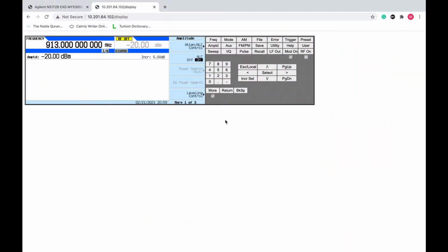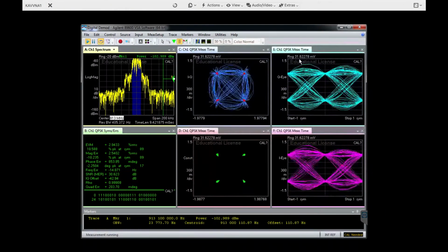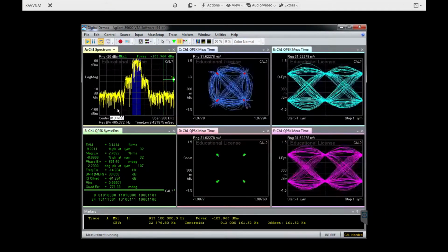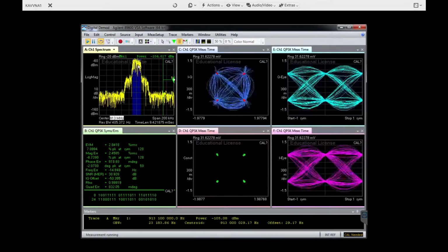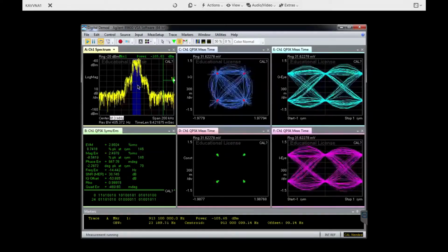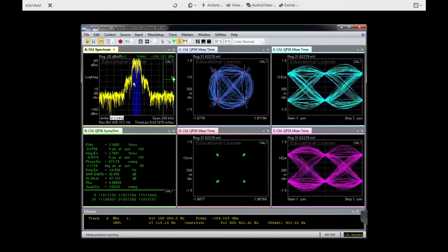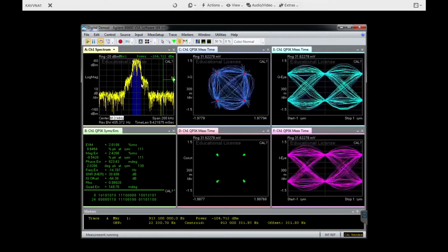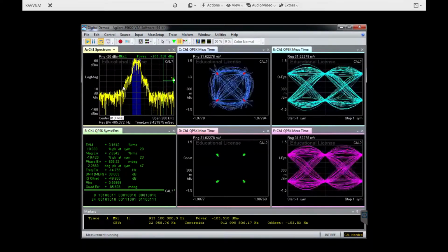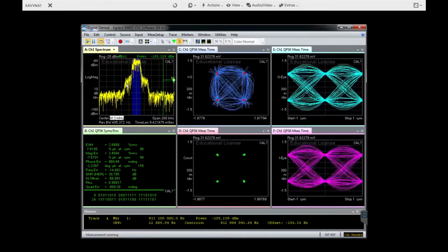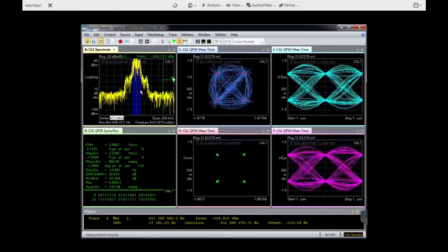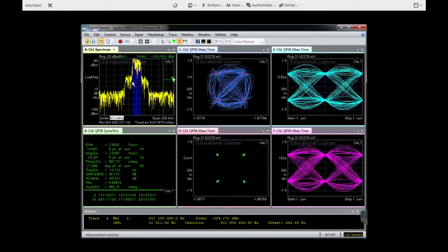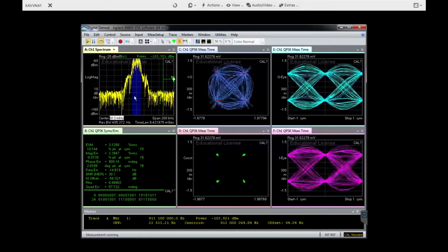So now let's transmit and see what we will be receiving at the receiver. At the fundamental frequency, which is 913 megahertz, we will be receiving the signal as usual, because this one is not suppressed by the filter. But the spectral regrowth caused by the LNA will not be suppressed by this filter, because it is very close to our desired signal anyway.